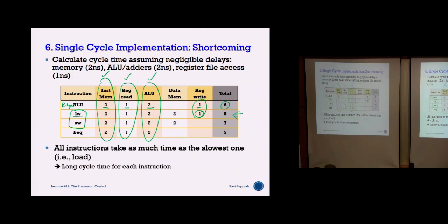So if I want to clock my processor, the fastest I can go should be 1/8 nanoseconds. That is of course the theoretical fastest that you can clock, for example this processor. If I clock it any faster than this, it means that some instruction cannot complete in time. Correct? So how do I make it faster, make it better?